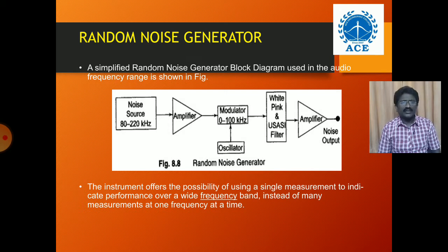By changing the position of the duty cycle, that is called the square and pulse generator. Actually here, for square wave you should maintain a duty cycle of 50%. Above 50%, up to 90%, that is called the pulse wave. So by changing the value of the duty cycle, you can modify the signal in the form of either square wave or pulse wave, according to our requirement.